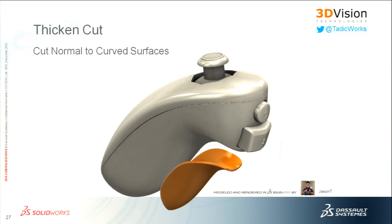Question? Besides surfaces, say take that yellow grip that you have there, and I need to extend those surfaces. Sometimes they don't extend, they'll wrap back on themselves. Is there a reason for that, and how do you correct it? Yeah. So when we're using the extend surface command, it's calculating the curvature at the end of that surface and trying to extend in that same curvature. So if there's any slight ripple in there at all, sometimes what it could do is, like you explained, curve right on top of itself.